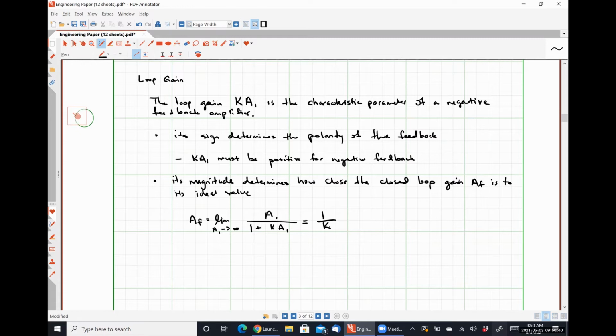If we have an ideal amplifier with an infinite open loop gain, then the transfer function is dependent only on the feedback network that's applied, right? Which is exactly what we saw when we analyzed op amps in circuits 1, and when we analyzed negative feedback op amps specifically in circuits 2. It doesn't really require that A1 is infinitely large for this to work. A1 can be on the order of a couple of hundred and will still be within a few percent of an ideal configuration. That's really good to know, because if we want to design a stable transistor amplifier with a particular gain, we can get there just by applying a feedback network and then making a few subtle corrections here and there to account for some non-idealities.